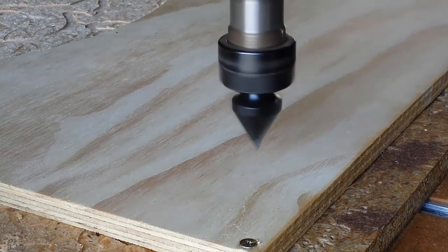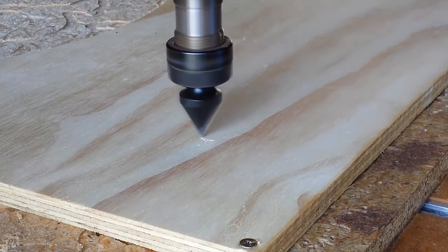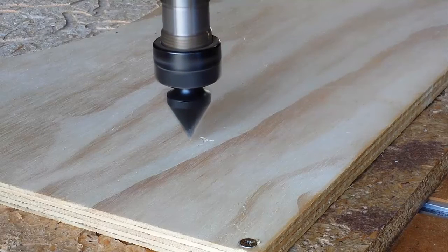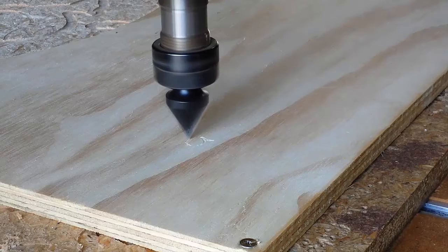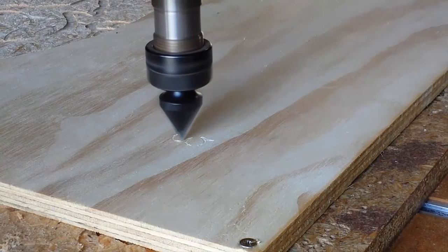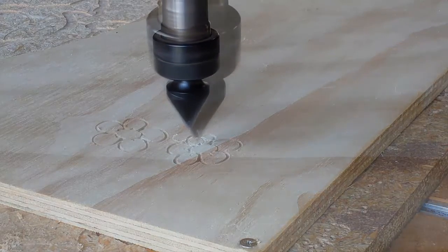When we use an engraving toolpath, the depth of cut made by the V-bit is controlled by two parallel vectors, such as we have in this example. If the two vectors are close together, the depth of the cut is shallow. The further apart the vectors, the deeper the cut.